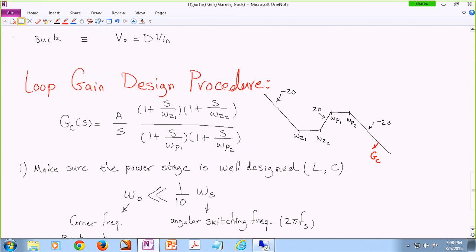So this is where we are looking at low frequency zeros and high frequency poles. Yes? How do we decide the order of appearance of the zeros and poles? Usually you put the zeros at lower frequencies to get a phase boost, and, as we're going to talk about, you put the poles at higher frequencies to get extra attenuation at higher frequencies. Otherwise, there is no point.